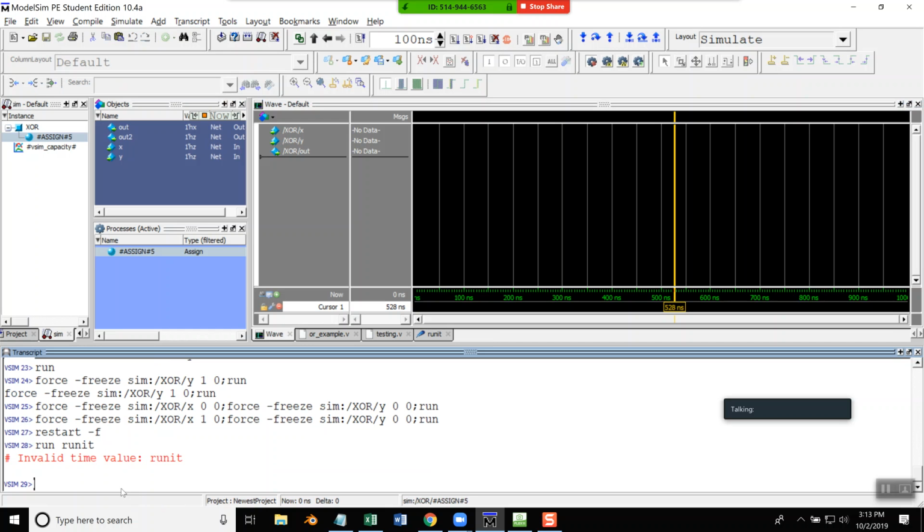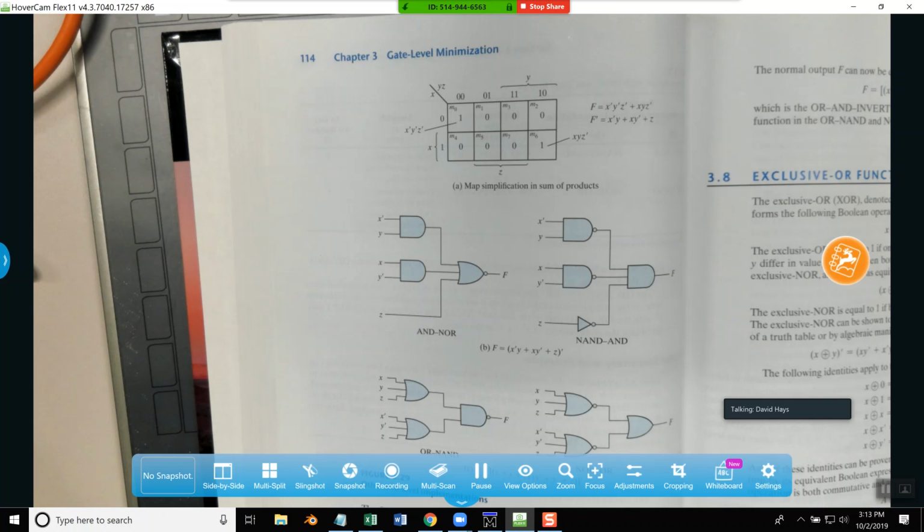For emphasis, clarity. Lines of text are terminated with a semicolon, and any text in between two forward slashes and the end of the line is interpreted as a comment. So again, the slash is used for a comment. A comment has no effect, just as you might expect. Blank spaces are ignored, but they may not appear within the text of a keyword. That makes sense. Verilog is case sensitive, which you'd expect.